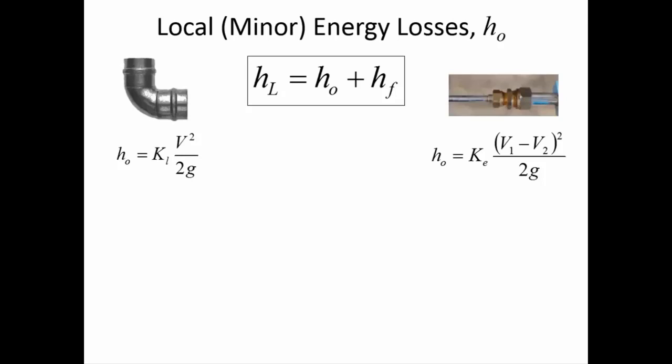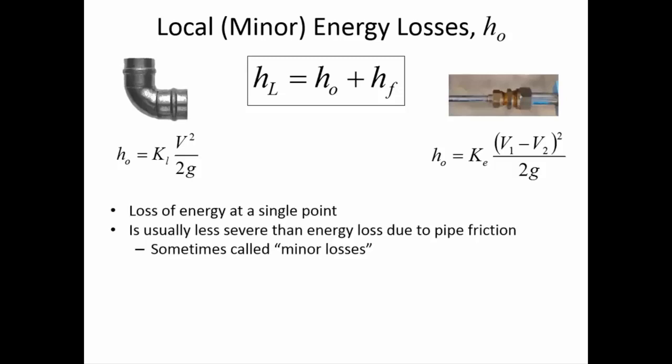If it's a small pipe going to a large pipe like this, obviously you're going to have the water here moving very slow, but then the water here is moving extremely quick and there's just a jet of turbulence as it enters that pipe. It's almost like water going into a tank, in which case it loses the entire velocity head when water transitions from a pipeline into a tank. And so a really extreme transition in diameters is essentially the same thing. We'll look at some K values on the next couple of slides.